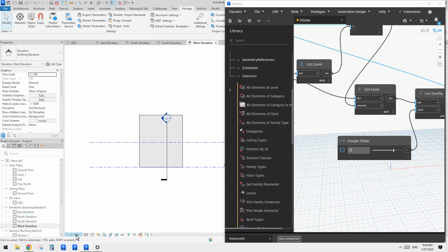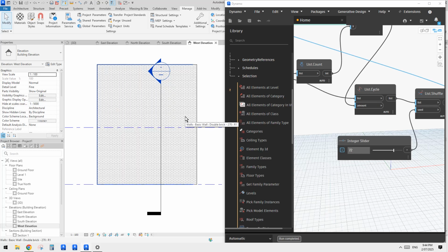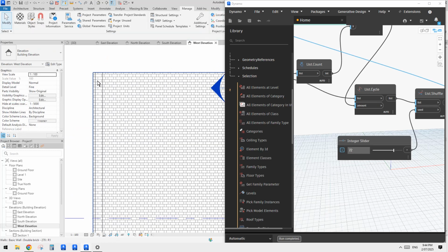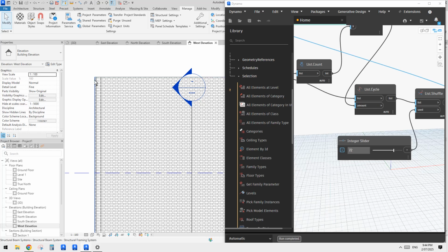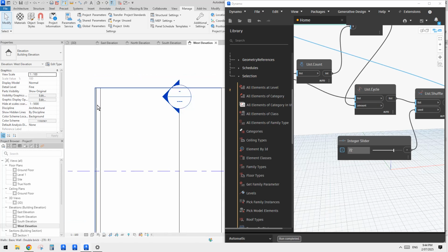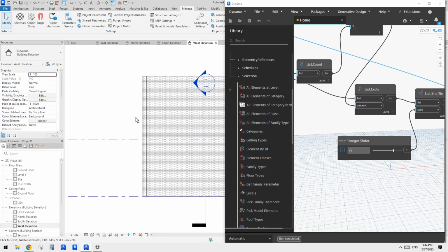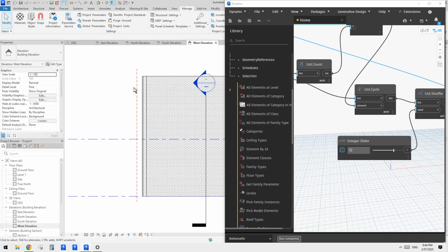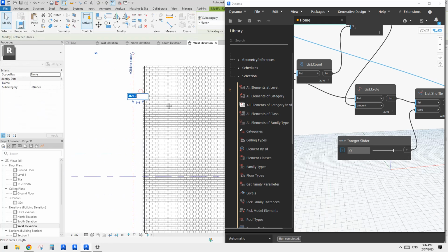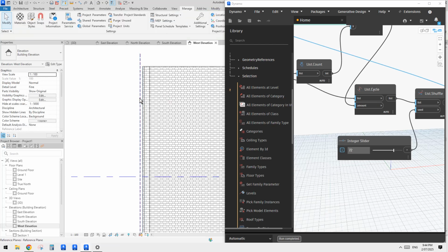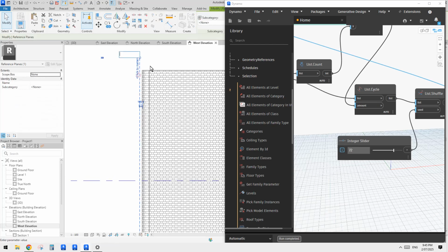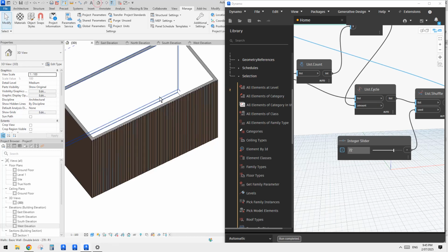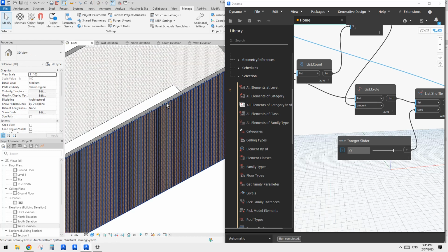Oh, it's not visible because, hang on, where are they? Oh yeah, WF. So yeah, wireframe, because they are in the wall. See here. So you can place a reference plane here, for example. I'll just place it maybe roughly 100, and also I'll give it a name so we can just change the work plane in any view.